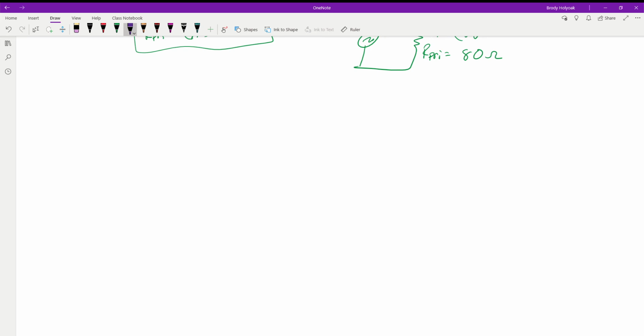Now the idea behind phase dots is, like you guys have been seeing with the RL circuits and RC circuits, different components put things in and out of phase. Sometimes we want them to happen first, sometimes we want them to happen later. So one of the ideas behind this is we can use a transformer to invert the phase of our signal. Basically it delays it by 180 degrees, or half the time of a cycle, because sometimes we want to do that deliberately.